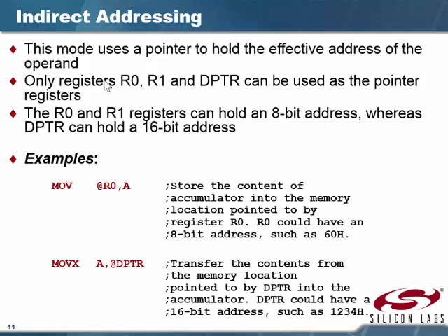That's why we can get away with only having an address for one register to contain the address, because static RAM, as the 8051 is defined, only has 256 bytes. That's all it has. And of which 128 bytes is gone because we're using it for the special function registers. So we only have 128 bytes to play with when it comes to the MOV instruction. Memory is fairly tight until we use the MOVX later on.